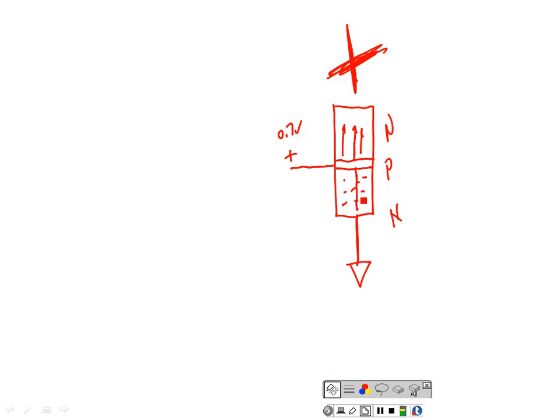You understand? And then it says, okay, I've got two ways I can go. I can go this way toward that little tiny P, or I can go up to that big old plus up there that's sucking everything up there, right? So what's it going to do? 99.95% of these electrons are going to fly right through that base because it can't make that turn, right?